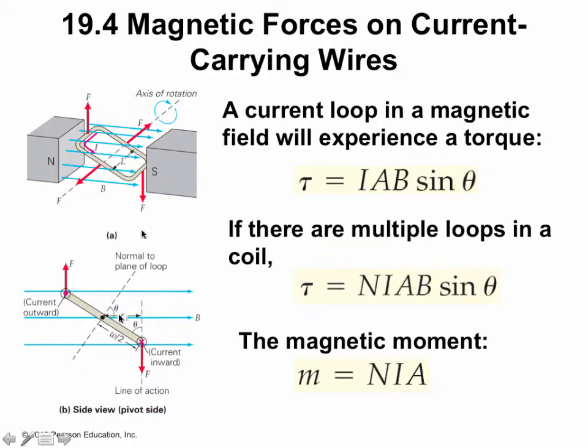So this would be theta, okay? And then theta is the same thing here. The current enters through the loop, but it kind of circles around the loop. And so based on the right-hand thumb rule, as the current passes this way, the force goes in this direction. When the current passes back down around through here, the force is applied downward. There's also a force that occurs here, and that's the axis of rotation. The magnetic field obviously goes from north to south pole.